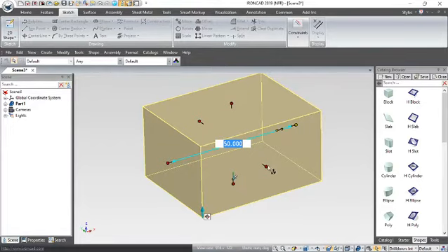If I move around to this one, you'll see that says that's the width of the part, and that one there is the height of the part. So if I pick this left hand icon, this button here, and say I maybe want to make that 175, that will extend this block 175 millimeters from this point here. So this one will remain fixed and this one will move.